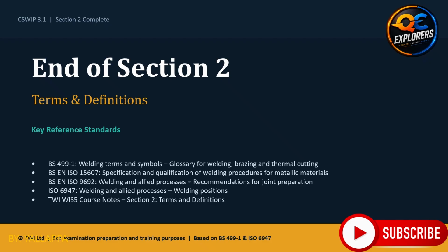Before progressing, make sure you can perform 3 tasks confidently. First, draw and label a butt weld and a fillet weld. Second, calculate throat from leg length and leg length from throat. Third, identify all 7 ISO 6947 welding positions. If you can do those 3 things accurately, you have a strong foundation for the next stage of the course.